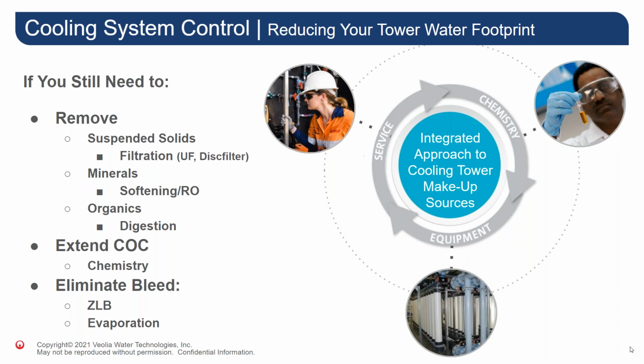If the mineral content of your water needs to be changed to control scaling potential, both cationic and anionic impurities can be removed through either full flow or partial flow using standard ion exchange or membrane technologies. If organics are a problem, both aerobic and anaerobic digestion technologies can help to remove these organics and create excellent quality water suitable for use in a cooling system, and again, doing so by removing disposable waste volume in the sludge that's generated.